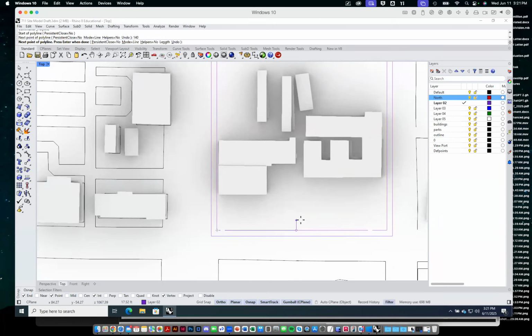What's the standard separation between buildings in the city? Not a clue, but in other cities, you can actually have a party wall and build right up. Maybe literally, it's pretty fun. If you have a certain partition, it has to be X fire hour. So you can't have a building next to you. You're going to have at least a 3-hour fire rating to whatever it is. But the other person is saying you're in low density, you have to come off. So yeah, some locations you find offset.